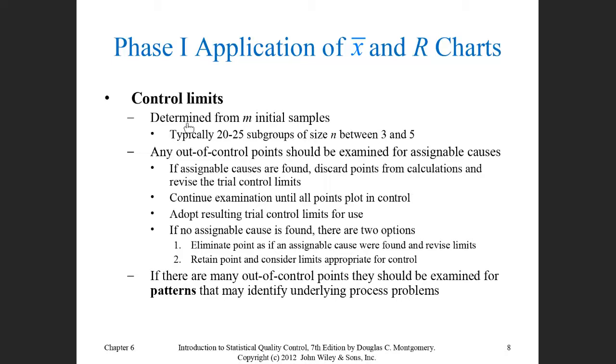From the sample size, we can determine whether an X bar R control chart will be used, or X bar S, or moving range. If the sample size is between 3 and 5, we use the X bar R control chart. The number of samples should be a minimum of 20 to 25. Usually 25 is ideal because it is economical and at the same time gives you enough readings.